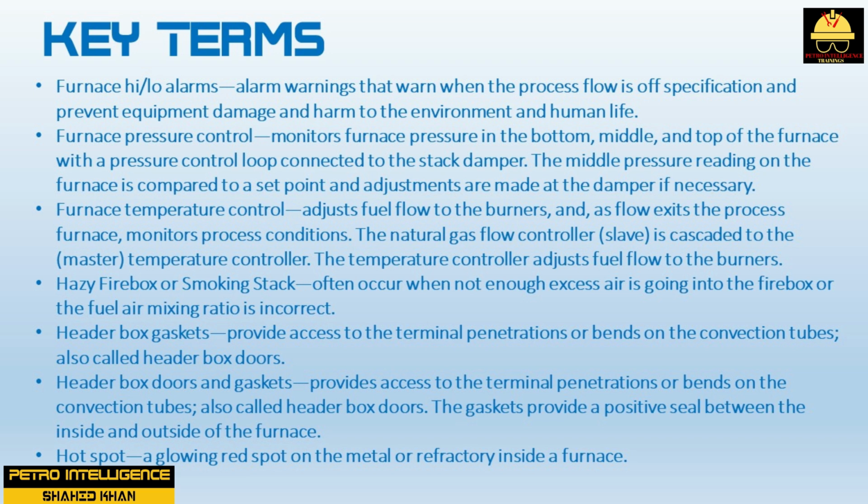Header box doors and gaskets provide access to the terminal penetrations or bends on the convection tubes, also called header box doors. The gaskets provide a positive seal between the inside and outside of the furnace. Hotspot, a glowing red spot on the metal or refractory inside a furnace.